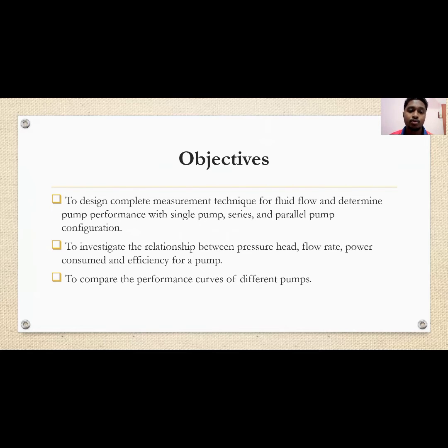So the objectives of this experiment are: first, to design a complete measurement technique for fluid flow and determine pump performance with single pump, series pump, and also parallel pump configuration. Next is to investigate the relationship between pressure head, flow rate, power consumed, and the efficiency of a pump. And finally, to compare the performance curves of different pumps.